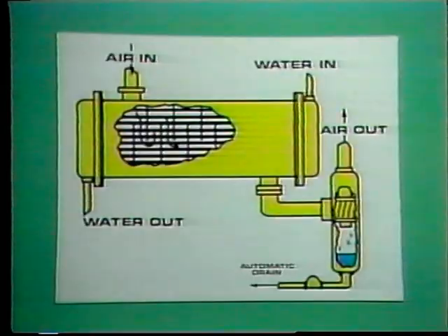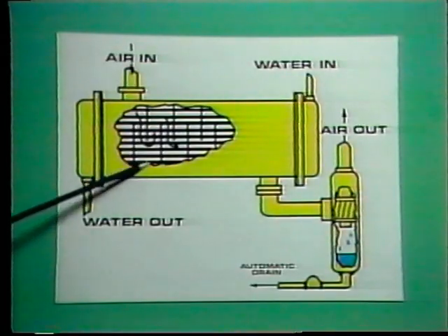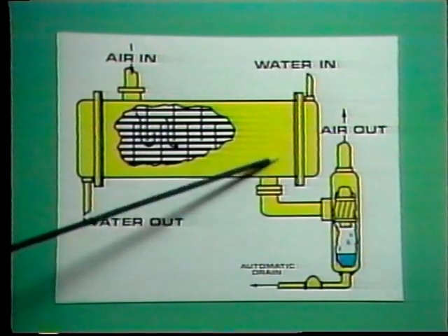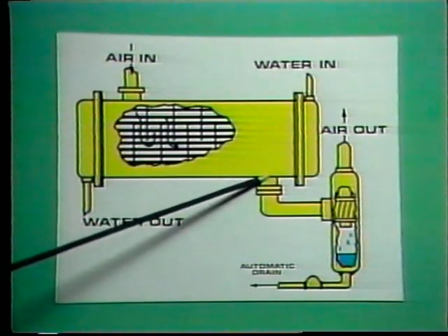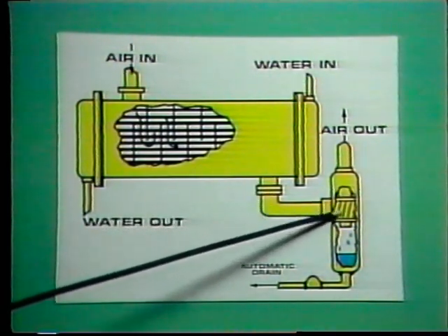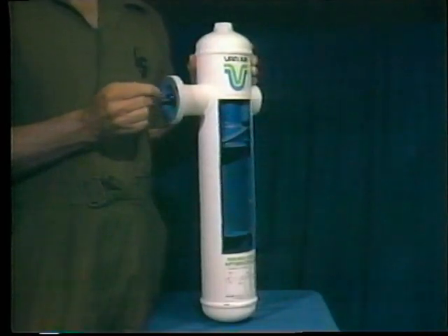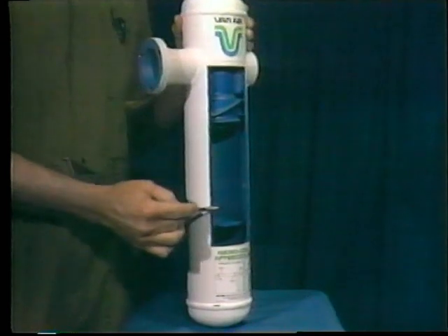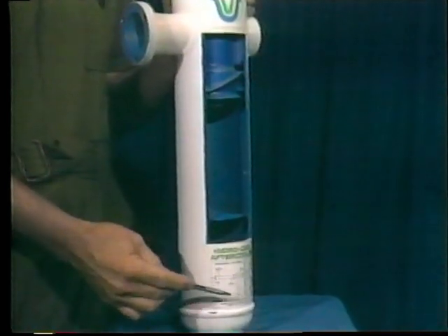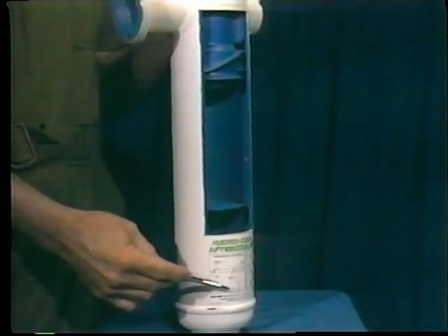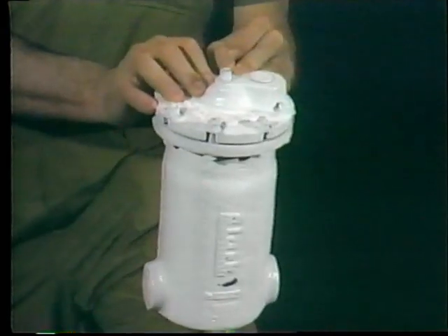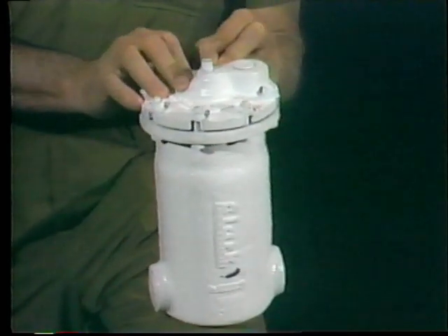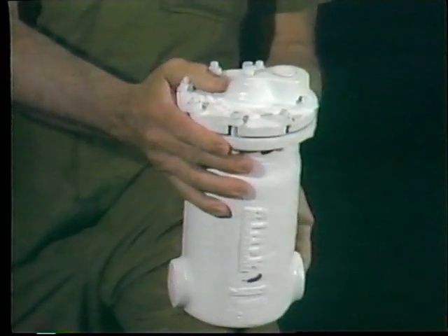That's because when air cools, it has less ability to hold moisture. So the water condenses or rains out in the form of moisture droplets. These droplets flow into the moisture separator, where water accumulates. Since with even a small aftercooler, we are talking about a fairly large amount of water, the separator should always be connected up to an automatic drain, similar to the one shown here.